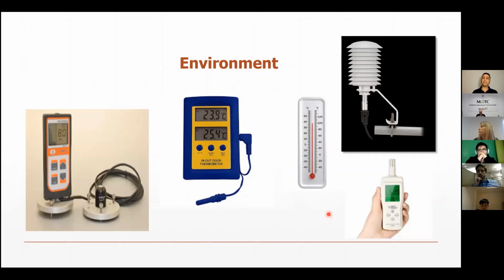Usually it will be related to radiation. So we have this simple tool for measuring PAR radiation. The grower can measure the PAR every hour in a particular day, or several times a day if you are suspecting that there is a problem, or just have simple monitoring of once a day: enter into the greenhouse, measure the PAR radiation inside the greenhouse compared to outside, write the percentage, and then we will know what the conditions in the greenhouse are.